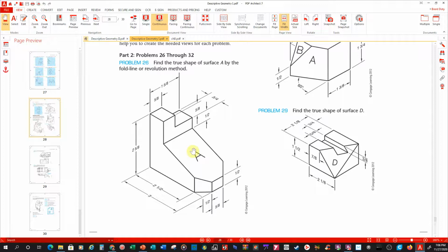So when we're talking about doing the true length of a line, you project off of one view and you go to the other view and measure. If you can get that straight, everything else is easy. You have to have a true length line before you can get a point view.